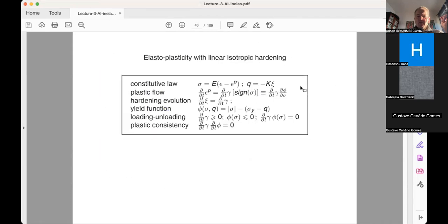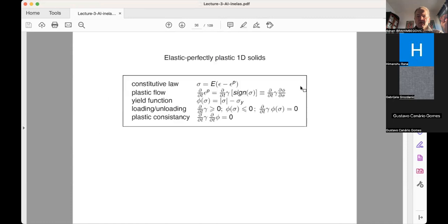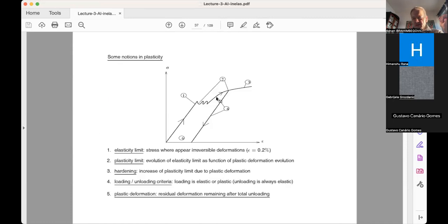This was the real behavior of the real material that motivated our work. So that certainly is just not a straight line. It could be something where you start having, let's say, nonlinear behavior, and then you have a maximum stress, the so-called saturation point. And after that, you go down to failure.